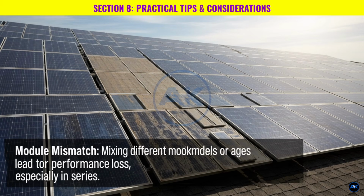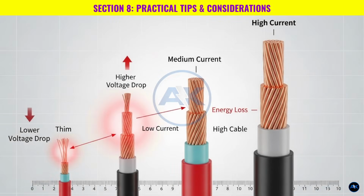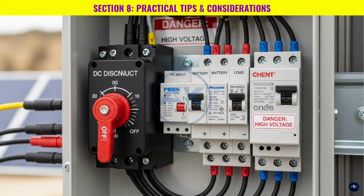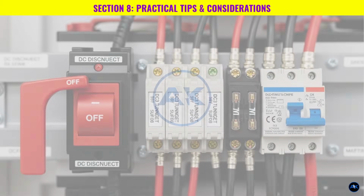Module mismatch. As discussed, try to use identical panels within a string. Mixing different models or ages can lead to performance loss, especially in series. Cable sizing. Higher currents require thicker cables to minimize voltage drop and energy loss, a topic for another video. Safety and disconnects. Always ensure proper DC disconnects and overcurrent protection fuses or breakers are in place. These are critical for system and personnel safety.